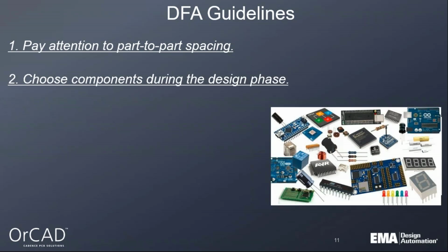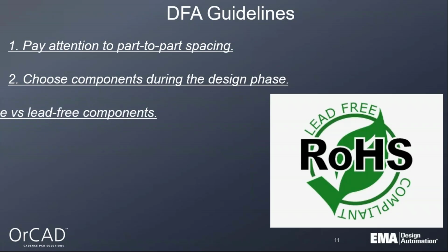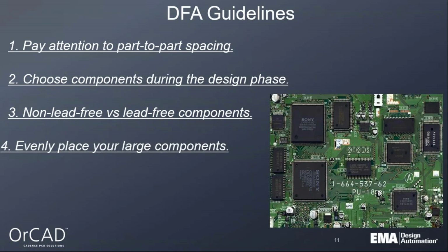Choose your components during the design phase. Make sure you're checking to make sure you have the right component. The component sizes from the beginning might change to different sizes as you're going through your design cycle. You want to make sure that you've got the correct sizes that you're dealing with. Non-lead-free and lead-free components: you never really want to mix lead-free components with non-lead-free components.